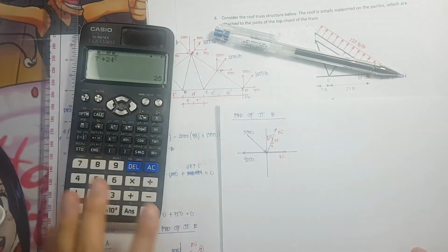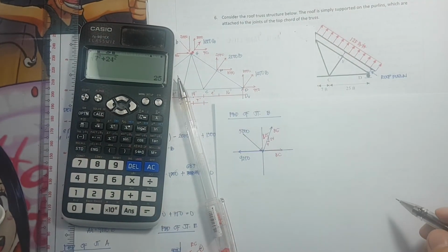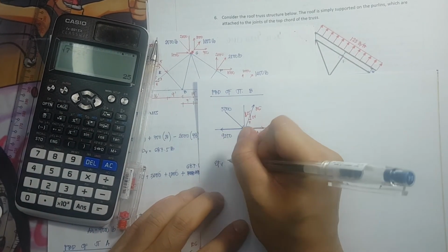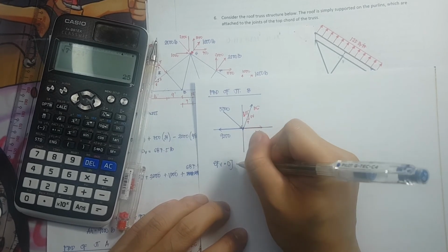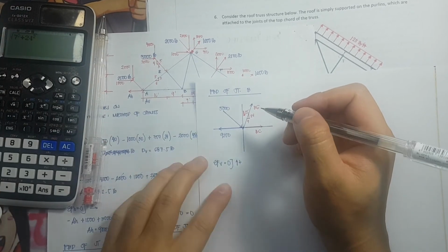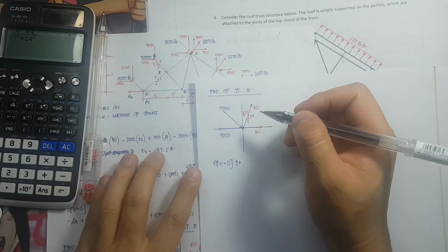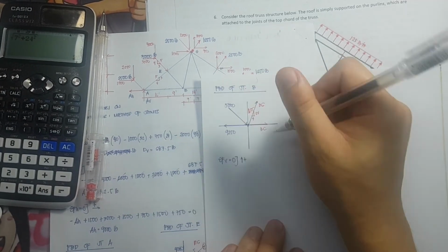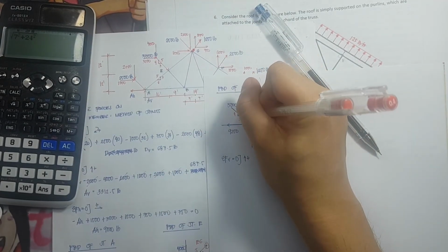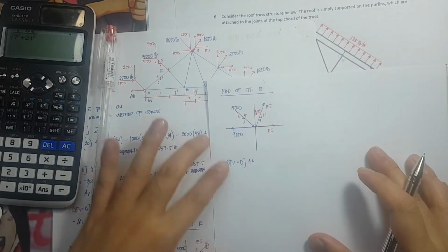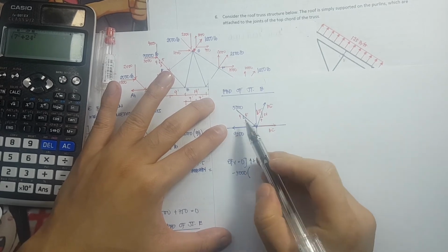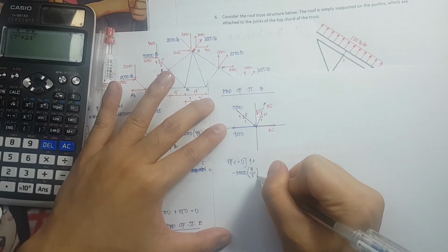So we can now solve summation of forces vertical. So let's start with vertical. So we will only have one unknown. So summation of forces vertical is equivalent to 0. All forces that are pointing upward should be positive. So what are those forces? We have 5,000 and the slope of that is 4 vertical, 3 horizontal, and 5 as the hypotenuse. So for the vertical, it is pointing downwards. So negative 5,000 times the vertical component of the slope, which is 4 over the hypotenuse of 5.